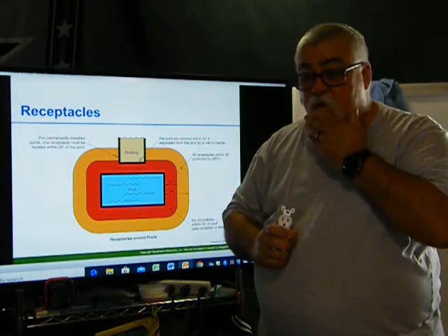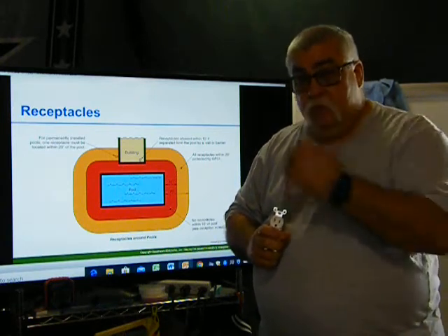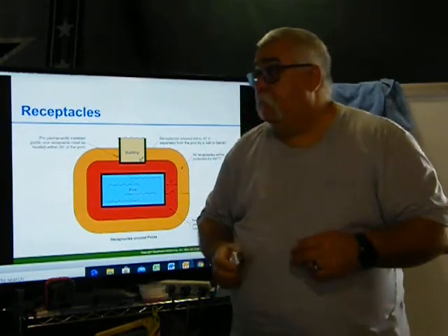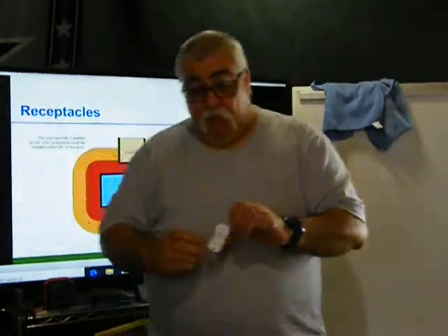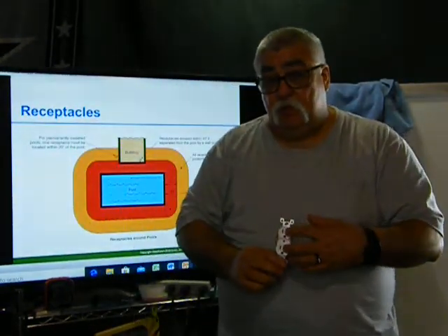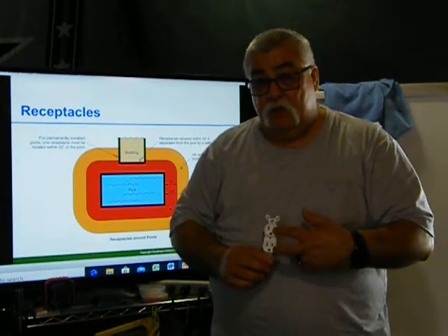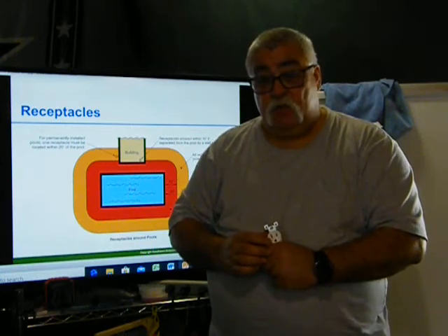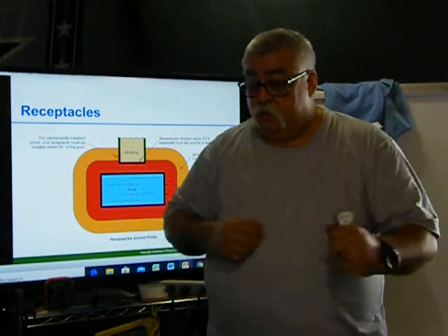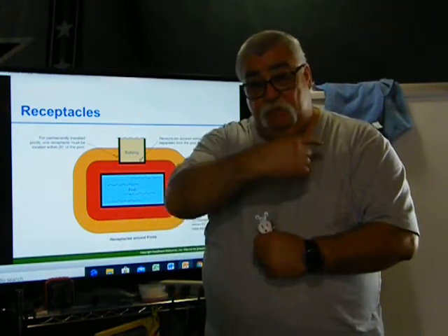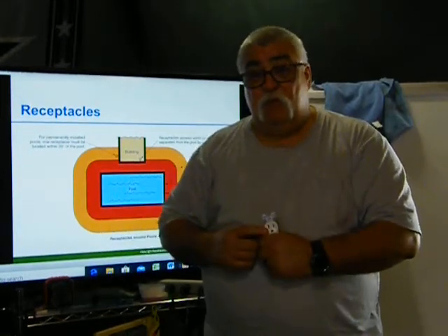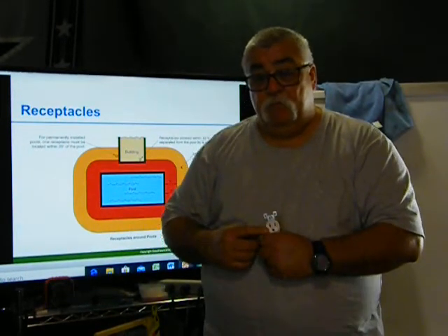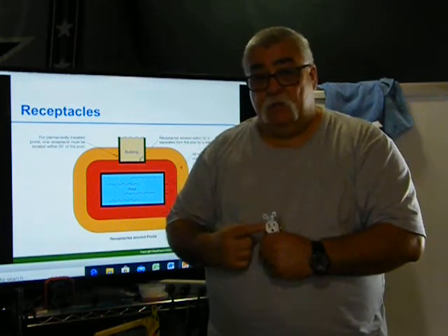So it's one of the safety cautions that you should take when you wire this stuff in. Okay, I can use a duplex 15 amp on a 20 amp breaker, 12 gauge wire, 20 amp breaker. But if I'm using a single, it has to be rated for whatever the circuit is. So if you're pulling number 12s across, guess what? You're going to put a 15 in with a 15 amp breaker? Okay, fine. No problem. Put 14s across. Now that way they can't upsize the breaker.